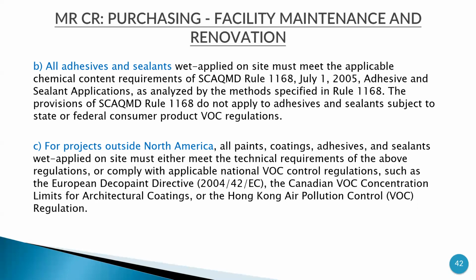For projects outside North America, all paints, coatings, adhesives, and sealants wet applied on site must either meet the technical requirements of the above regulations or comply with applicable national VOC control regulations, such as the European Deco Paint Directive, the Canadian VOC concentration limit for architectural coatings, or the Hong Kong Air Pollution Control VOC regulations. There are regulations from across the globe.